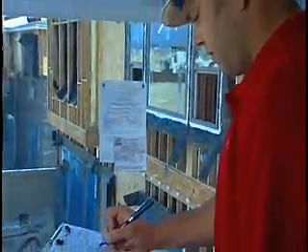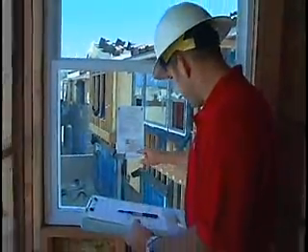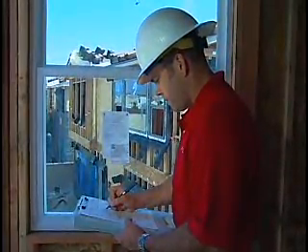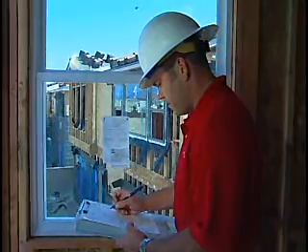We had one test that was done in Roseville, California, and you had two identical houses, and the only difference between the two was the windows. The one with the really good windows only took a 2.5-ton air conditioner, whereas the one with the standard windows took a 3.5-ton air conditioner to do exactly the same job. So that also saves money for the contractor because it costs money to upsize those systems. That's right. The larger system costs the builder more or the homeowner more, and so you really ought to get the right size. Don't just go by square footage. That's the standard thing to do.